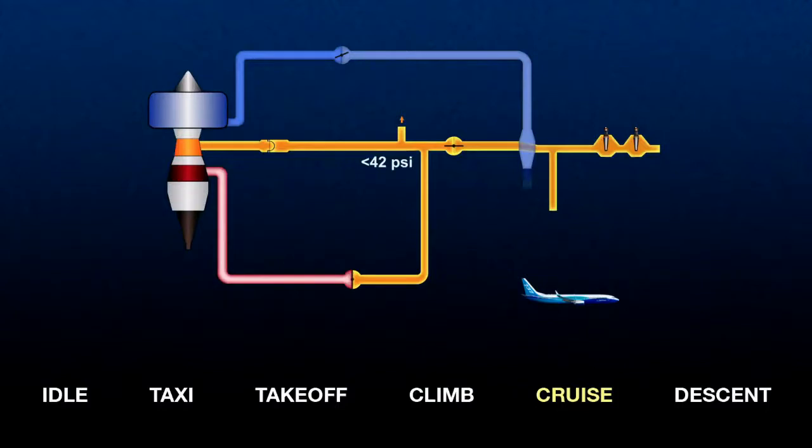If the airplane is lighter, the throttle settings may be lowered, reducing the 5th stage air pressure enough so that the HSV will open and the system will again be using 9th stage air. Note that depending on altitude, the HSV may open even at the beginning of cruise.